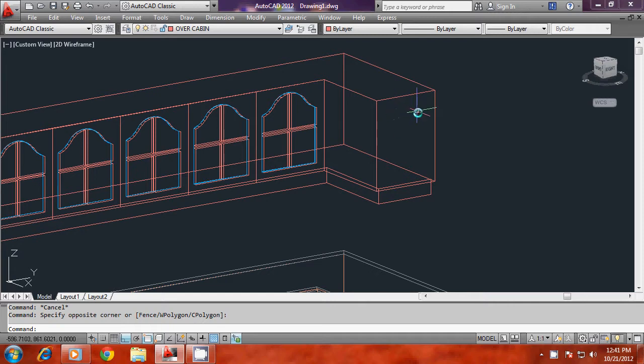So what I'll do is I'll move this particular face in the negative x-axis direction. You can look at the icon here in the negative x-axis direction through a distance of 30 units. So if you want to work with the face of a solid model which is already created, the command is solid edit. So I'll give solid edit command, and a solid model can be edited in various sub-object levels. You can edit it on the face level or on the edge level or on the body level.